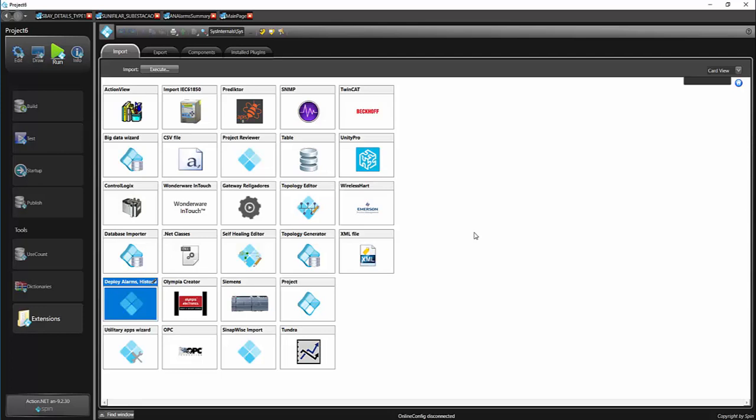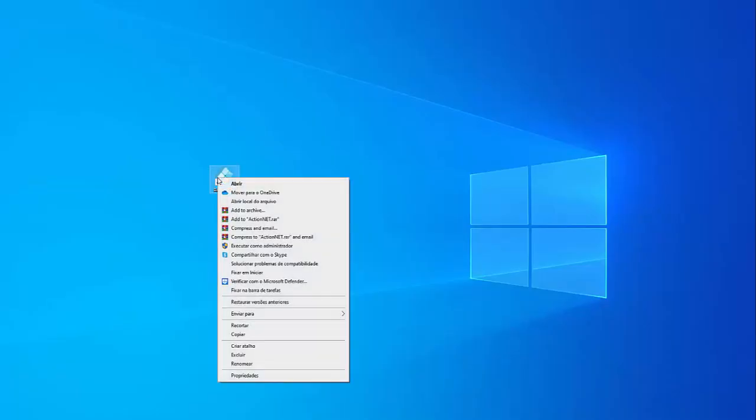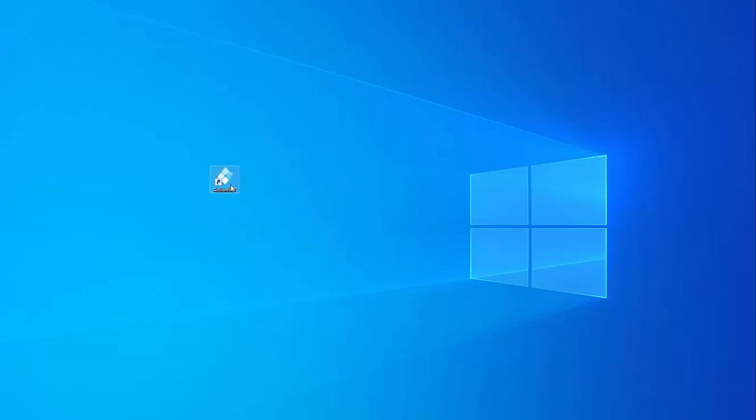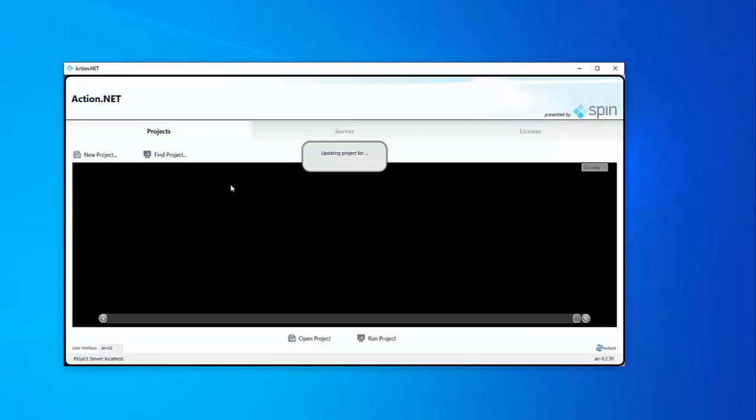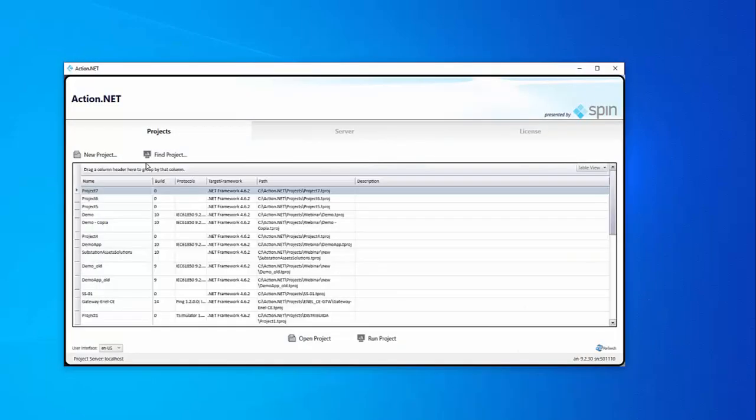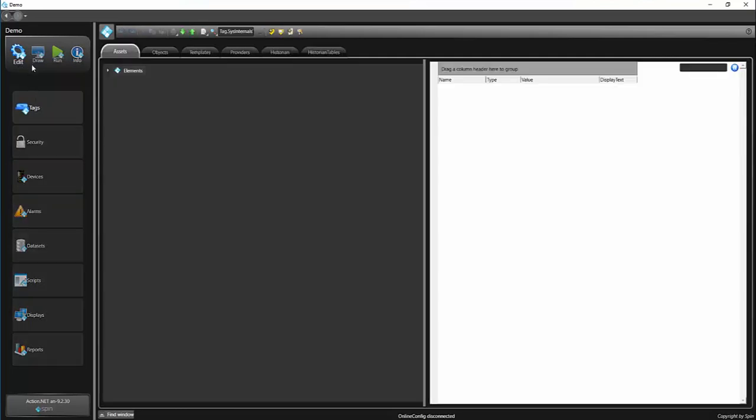Let's close this application and open the demo application shown earlier. In this application, to show the simplicity of creating a bay, let's add a third feeder bay, and then let's run the demo. When opening the demo application, in the Assets tab, we have 5 bays in Asset SS: 2 feeders, a 13.8 kV bus, a 69 kV line, and a transformer.